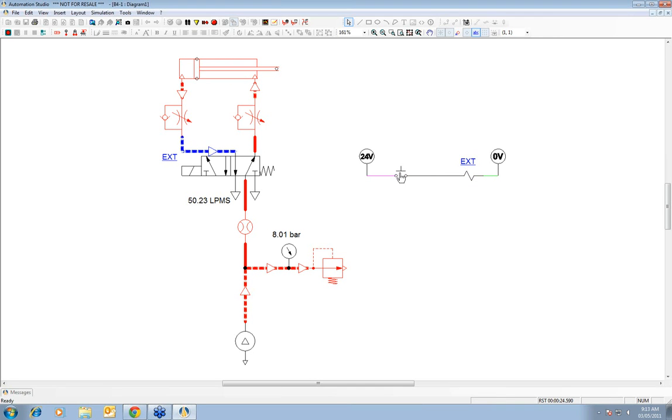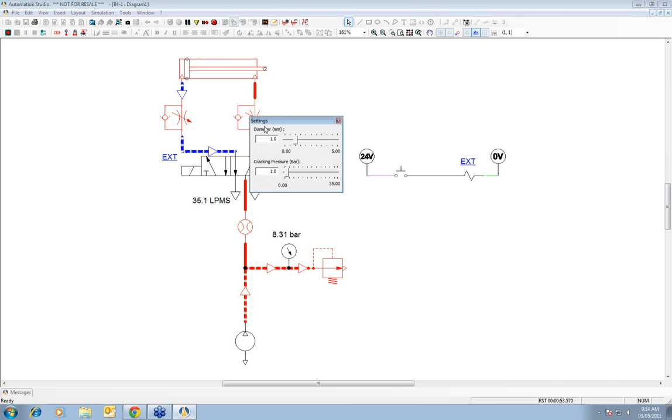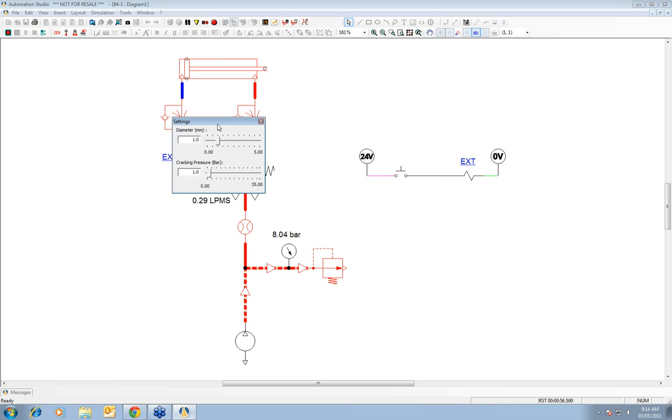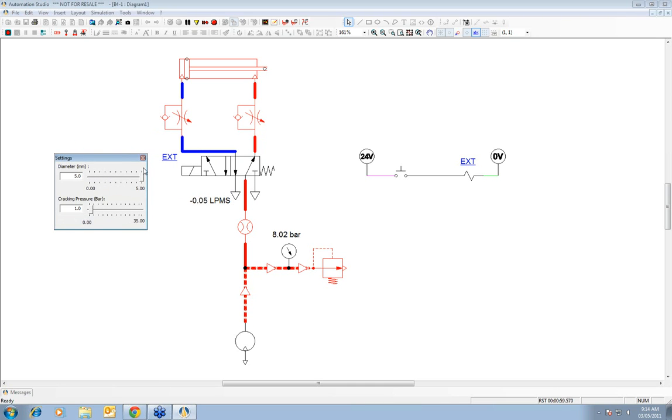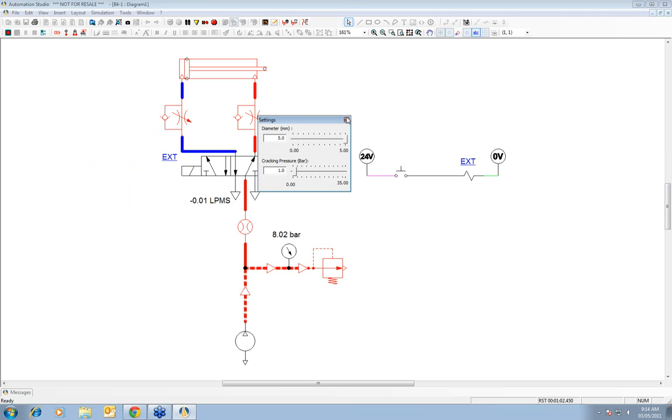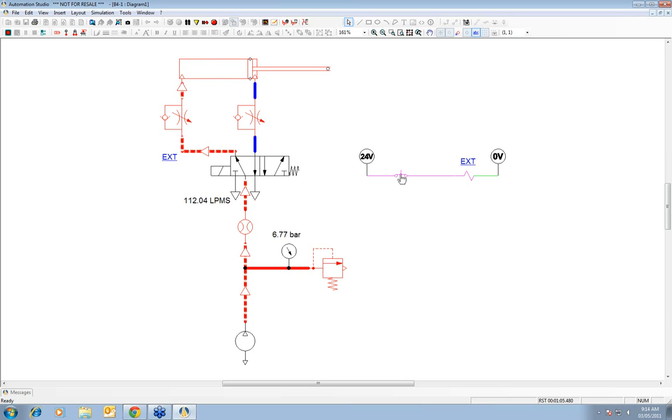because if you just click once, there's a spring return inserted in that push button. So if you're not holding down the push button, it's going to return all the time. If you want to hold it down, you click once, you hold your click, you move away. When you do not see the hand again, you release your click and the button stays pushed down, okay? So right now I'm controlling the directional valve that I have here by using the push button. And of course, if I want to change the speed on these meter-in, meter-out units, I can simply increase those diameters, and now I should have something that goes quicker.